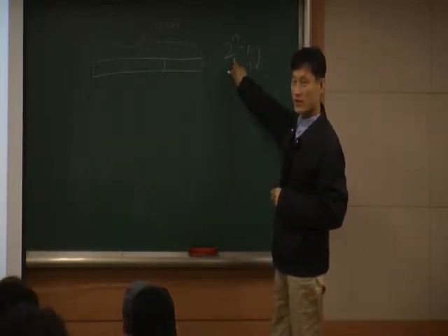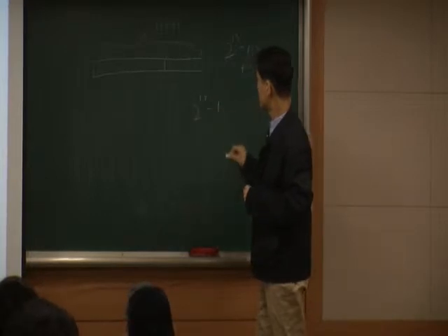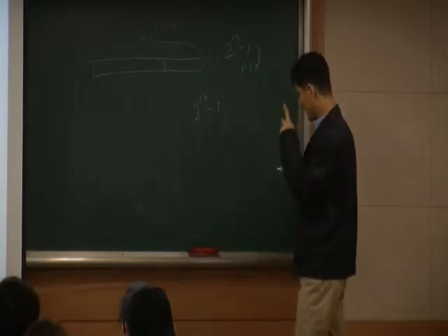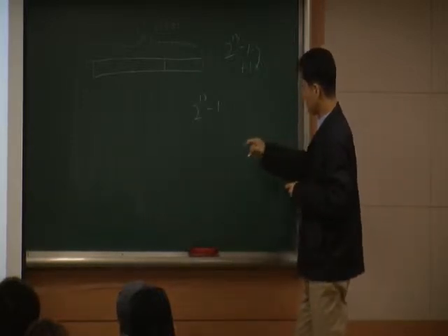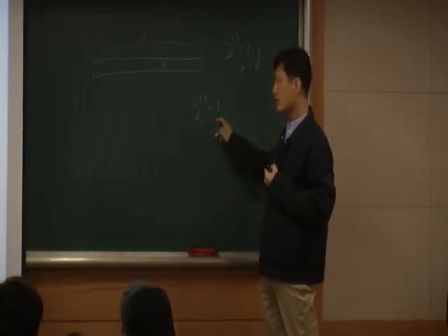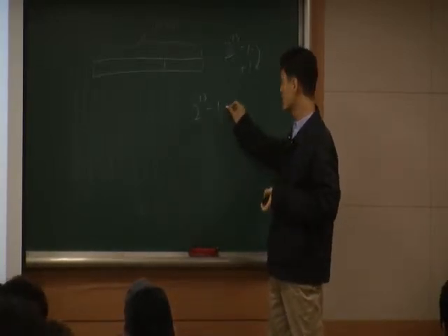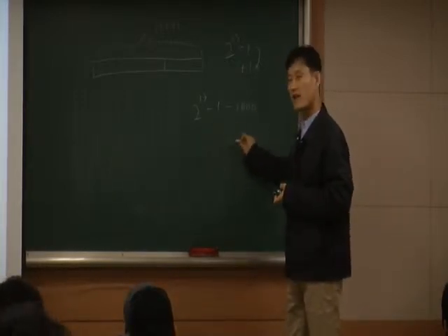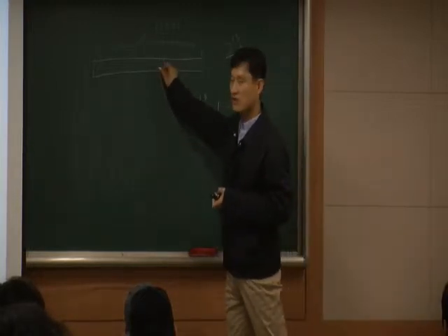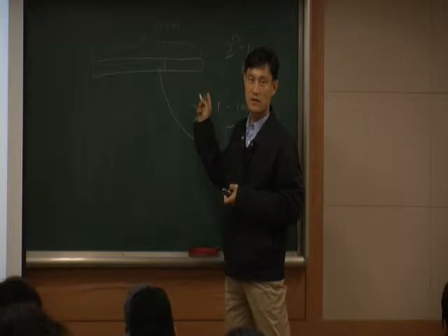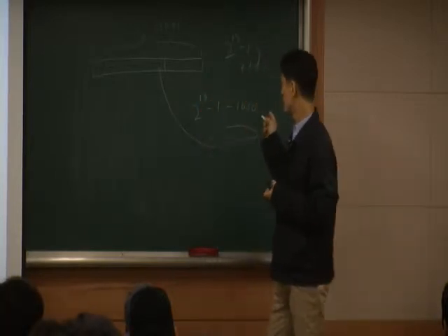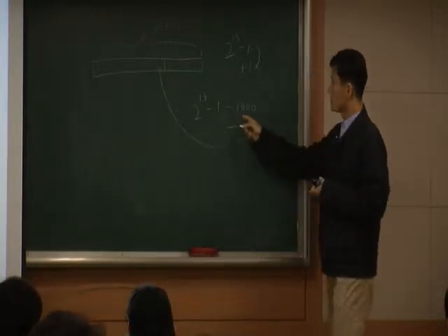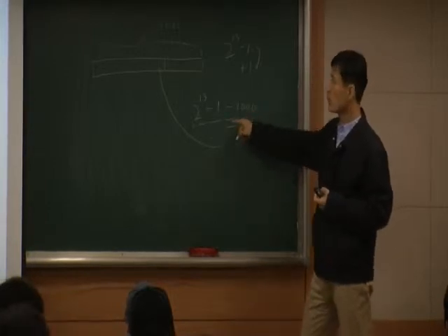This is the maximum value we have, right? From this value, let's say I want to count 1,000 pulses. I want to subtract 1,000. In that case, you get some value, right? You're going to write this value as an initial value into the timer. That's what you want. Actually, plus 1. Yeah, I think that's right. So this is the initial value you want to write into the register.